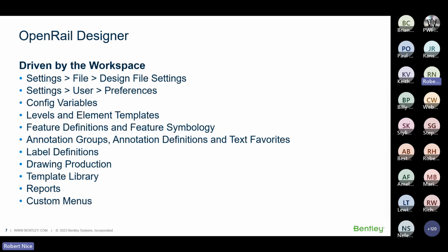Drawing production has changed. In the past, you would go, I don't know, evaluation, profile, create profile. Pick your geometry, click on the screen, pick a preference probably, click on the screen, and it's drawn your profile. And maybe then you go evaluation, profile, annotate profile. And again, you'd probably pick a preference, and I want to annotate, I don't know, the chainage, cant, horizontal, vertical, and whatever else. You pick from that list and it applies it, and that's just drawn in MicroStation.